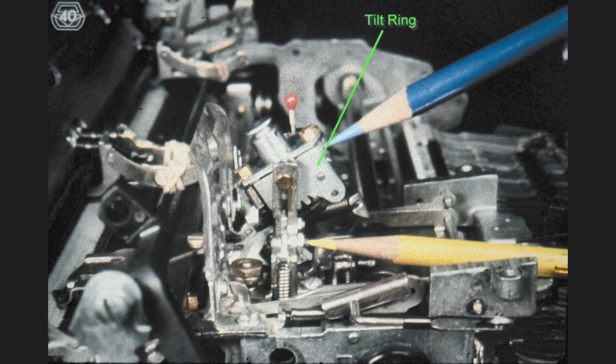By turning the screw which constitutes the pivot point for the tilt detent at the yellow pencil, and also the screw located right behind the yellow pencil, we are able to restrict the lateral movement of the tilt detent sufficiently so that when it is engaged with the V-shaped cutout, the tilt ring is prevented from tilting or rotating in a vertical plane. When tightening the screw indicated by the yellow pencil and also the screw immediately behind it, we must be careful not to create any binds for the detent. Check the lateral play of the tilt detent on your machine.